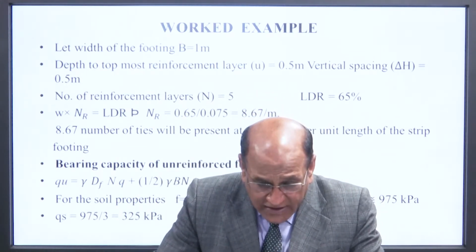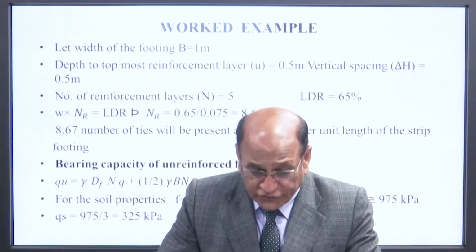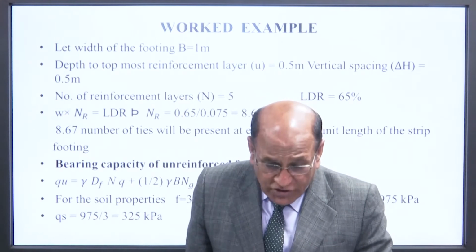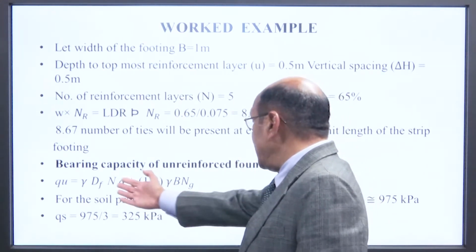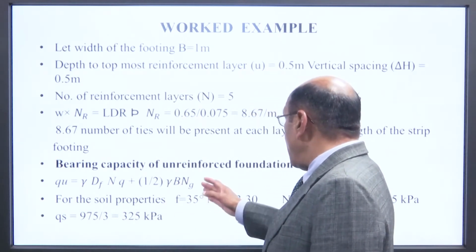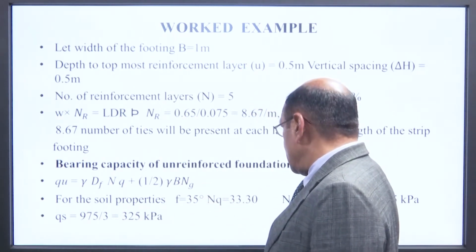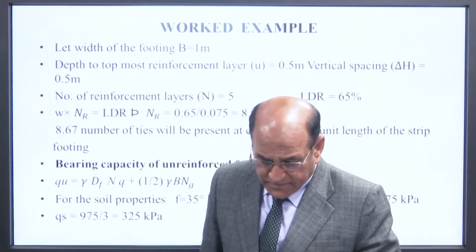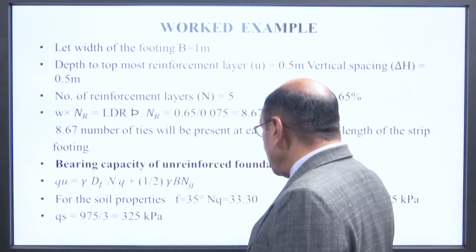Now, the bearing capacity of unreinforced foundation, qu is equal to gamma Df into Nq plus 1 by 2 gamma B N gamma.